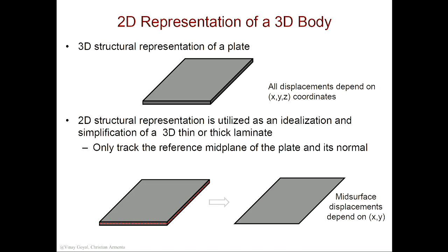So it's not 2D, because this particular element can actually deform in all 3 directions: through a thickness, in plane, all directions, rotations, and so forth. So it's different from 2D from that perspective. In 2D, we only have deflections in the plane of the page, okay, and axisymmetric. And I want you to also notice that the displacements in the mid-surface only depend on x and y. Only x and y.